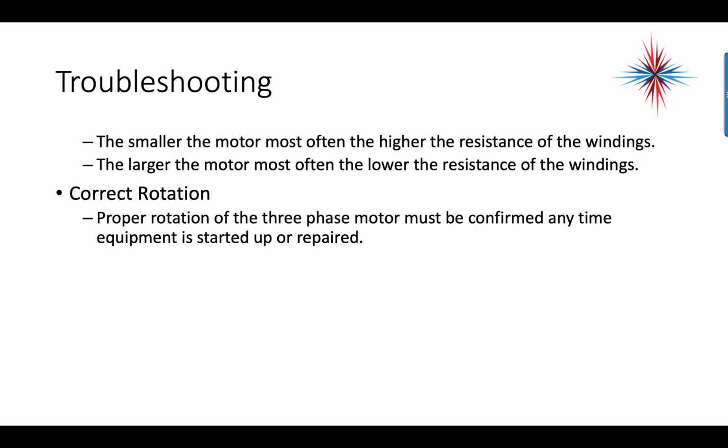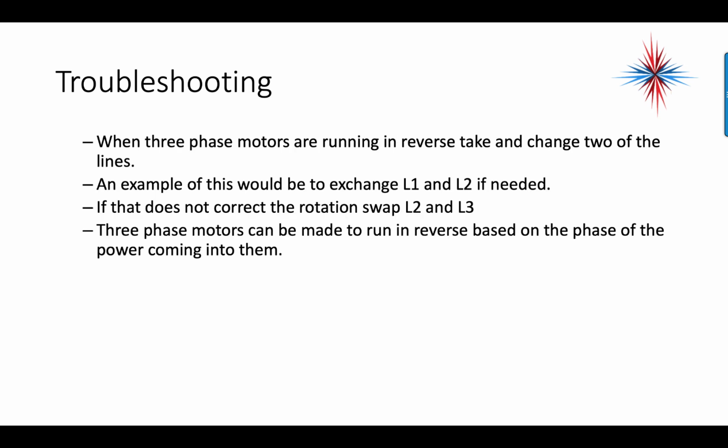It's also very important with three-phase motors to check for proper rotation. The proper rotation of a three-phase motor must be confirmed anytime the equipment is started up or repaired. I actually went on a service call on a packaged rooftop air conditioning unit where the customer was complaining of no cooling. All the motors were running backwards because whoever started it up did not check for correct rotation.